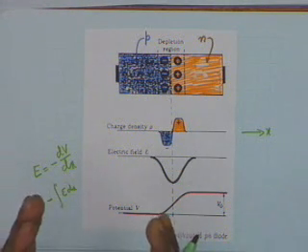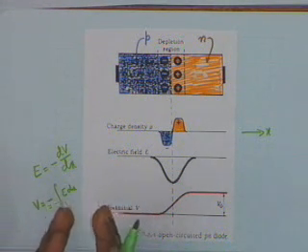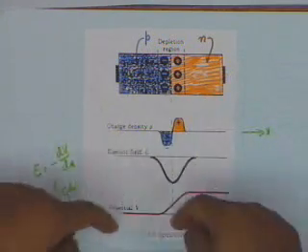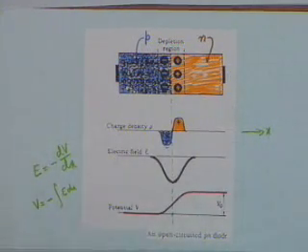That is, when two regions P and N are brought in contact with each other, there is a potential difference, and the potential difference is of the order of 0.1 volt. It is a very small voltage. Question: can it be used for driving a current through an external resistor? If I connect this to an external resistor, shall it? No.